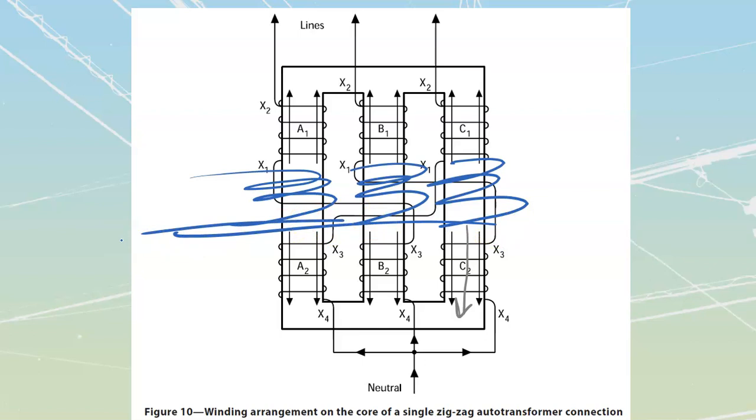But we're not going to worry too much about that. Do I want you to stress much over the complications of it? No. To be honest, I'm skimming this subject over here on the zigzag autotransformer. If we have time, we can definitely go in depth, but it's going to be about 2 hours of, we actually have to go into the vectors intensively in order to completely explain what's going on inside of these. Are you going to do that in the field? Absolutely not. What you're going to do in the field is say, hey, I need a zigzag autotransformer. I've got this issue with some weird harmonics coming off my 3-phase loads, and I want to be able to filter them out.